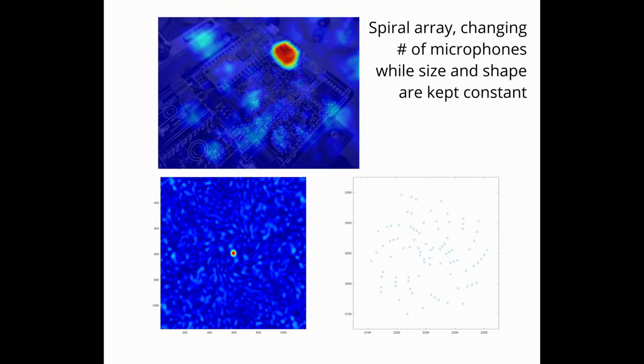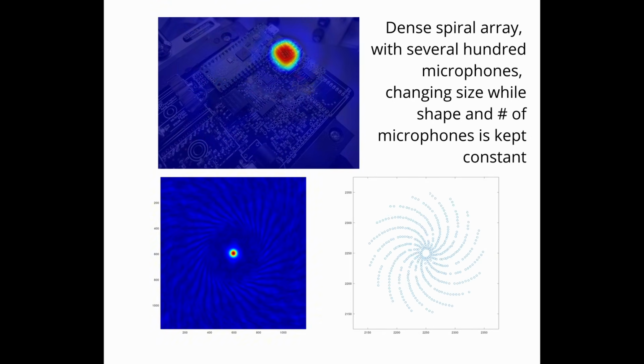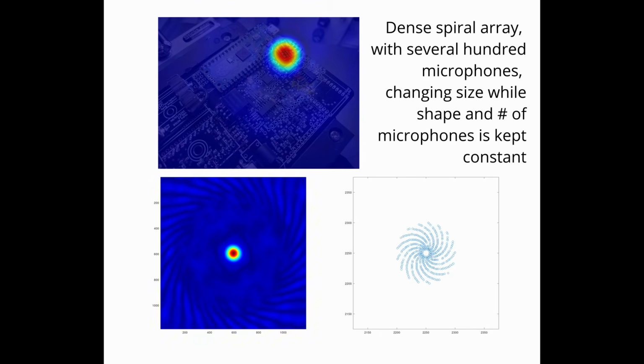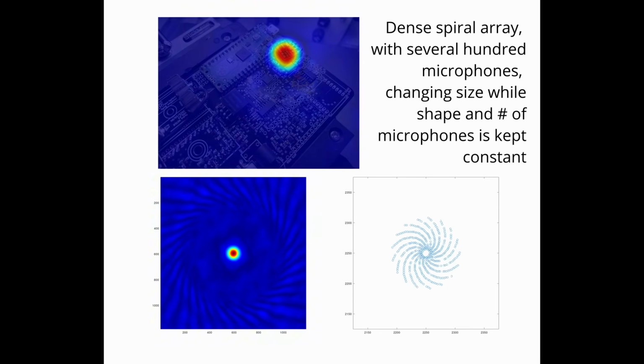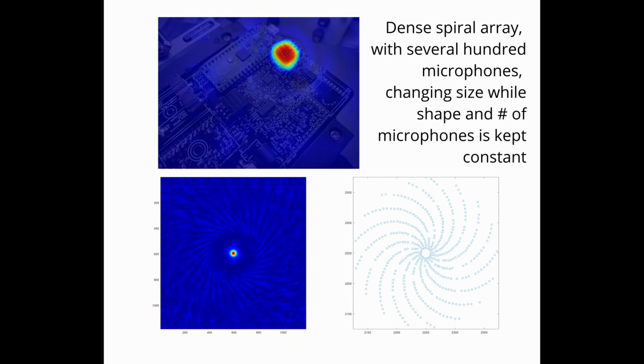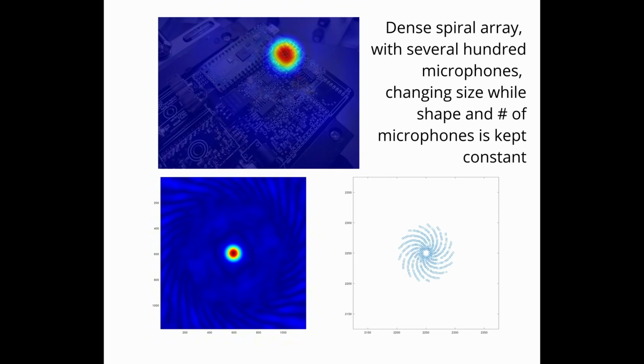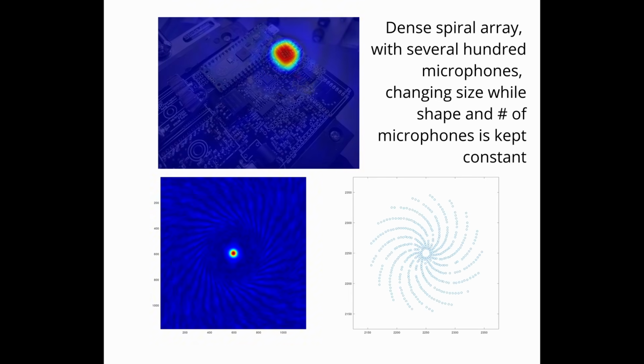Hopefully with those, it's apparent why pretty much every commercial acoustic camera uses basically this arrangement. It's a good balance of artifacts and spot size, and spreads out most of those artifacts into a big dark ring, so it doesn't cause strong false points or distort the spot shape significantly.